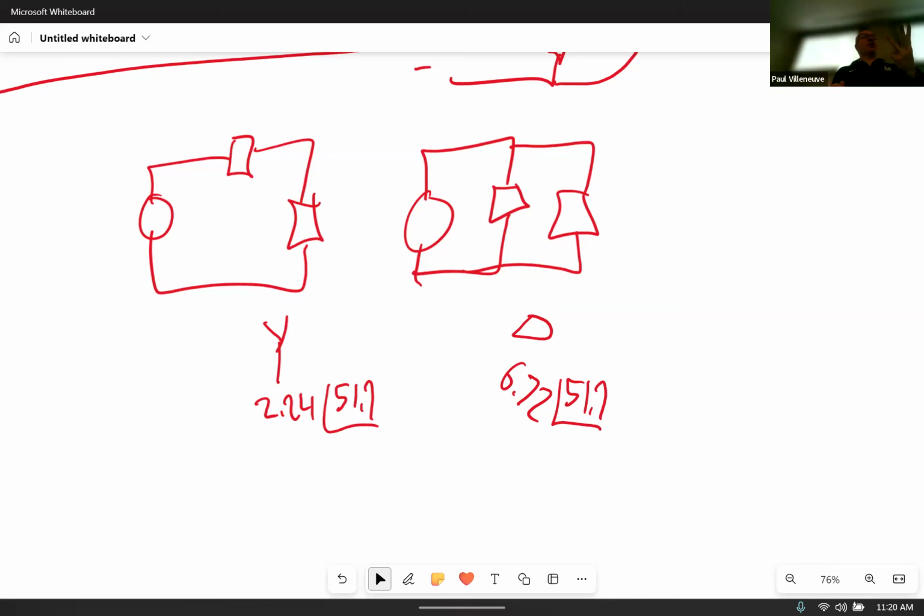I actually have three resistors. So most of the time in a three-phase system, I call it a resistive load bank or a capacitor bank, because that means it's three capacitors. It's a bank of capacitors. It's not one capacitor, it's three of them. So when I say the resistor in a three-phase circuit, I might be misspeaking, but it should be the resistor bank in a three-phase circuit.